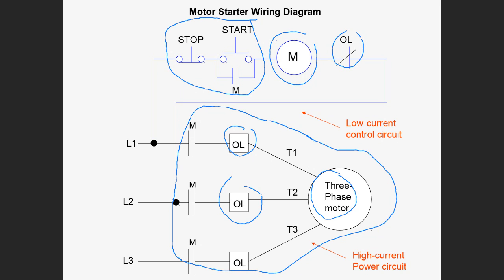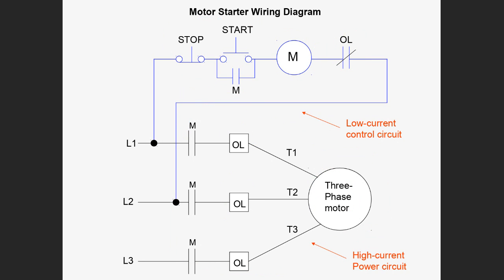So a relay is a basic on-off switch that's electromagnetically controlled. A contactor is a heavy-duty relay designed to switch heavy loads, and the loads are typically three-phase. And the motor starter is a special type of contactor with its own built-in overload relay. And so typically this is what you would connect to a PLC to start or stop a motor, circuitry like what you are viewing right now.